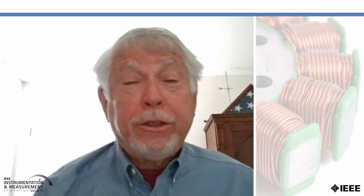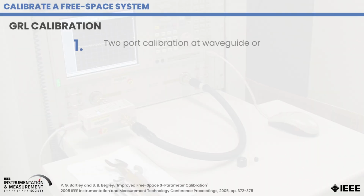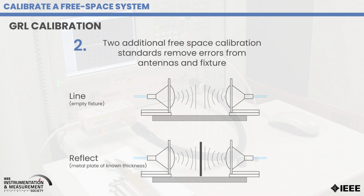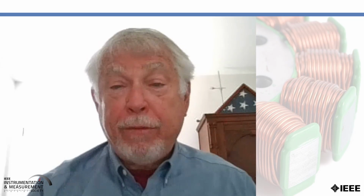Another possibility is to use a GRL calibration. It is a two-step process. First, you do a calibration at the end of the cables that you're going to use to connect to the antenna. The second step in the GRL calibration is to measure a through and a metal plate. Now, this system uses time domain gating in order to estimate the value of the directivity. So that's two less error coefficients that need to be determined. By doing this, we set the reference of the measurement at the surface of the metal plate.